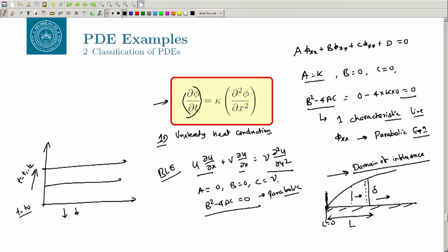Similarly, in the boundary layer equation, whatever happens at the edge of the plate will propagate and decide how the boundary layer is going to form on the flat plate, right. So, your delta x you can determine based on the immediate past history or the length of the plate. Okay, that is what you mean by the parabolic equation, right.